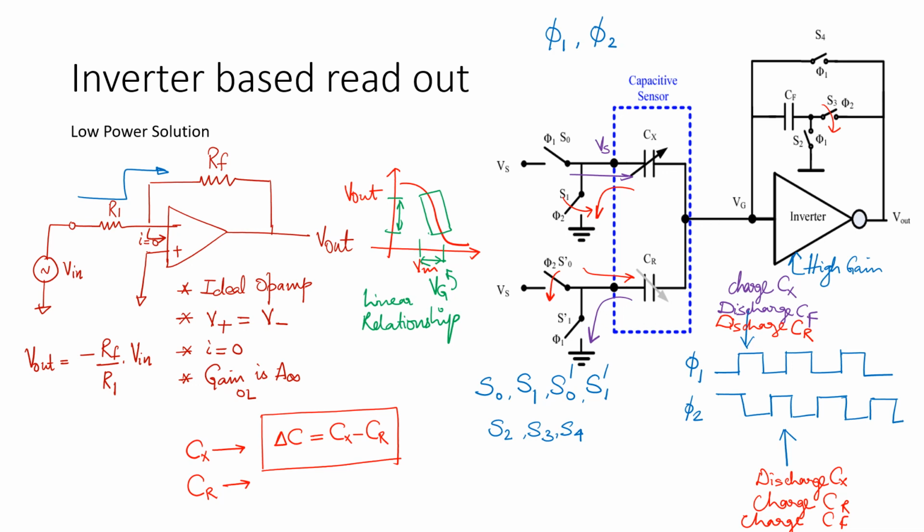Which is a very narrow region. So you know that this is a very narrow region. So the variation in Vg is very small. And as the variation in Vg is very small, you will come to know that the amount of capacitance change that is needed is small. So what is the activation that you need to give as an input Vs? This activation voltage for a sensor will need to be carefully controlled and calibrated. So a very narrow input change will give a very large output change. So this will also help to understand what is the value of input capacitance that you can measure.